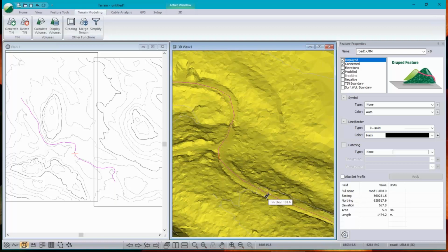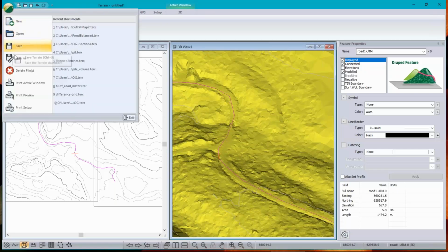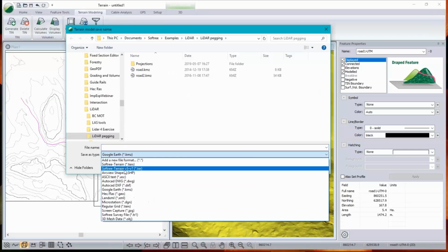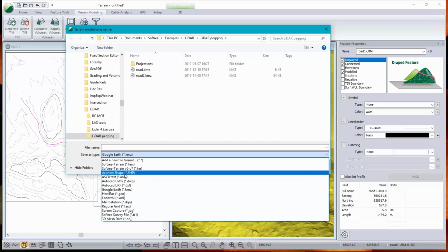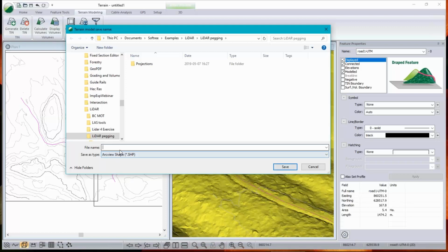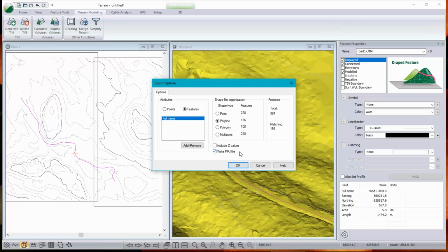And everything is georeferenced. And now I can peg in a road, I can draw a polygon, and I can export any of those features back to Google Earth if I want, or bring it into some other software, like, for example, ArcGIS. We do file save as shape. Where is it? There we go. So you can take your line work, you can export it back to shape, and it will create a projection. So that shapefile will be georeferenced, right? PRJ, that will be a georeferenced shapefile.